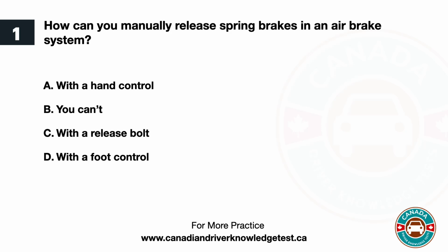Question 1. How can you manually release spring brakes in an air brake system? A. With a hand control. B. You can't. C. With a release bolt. D. With a foot control. The answer is C. With a release bolt.